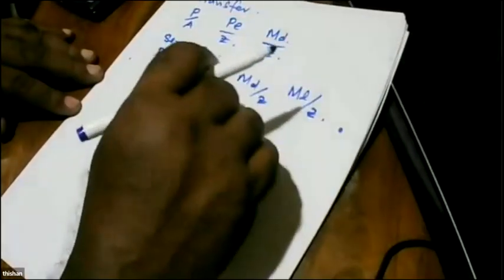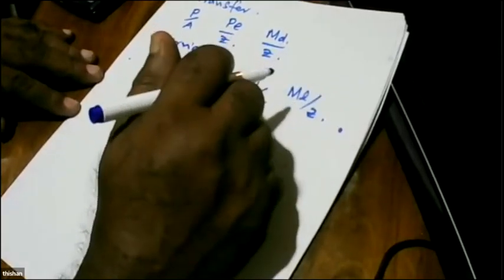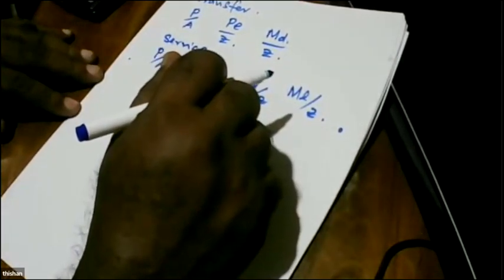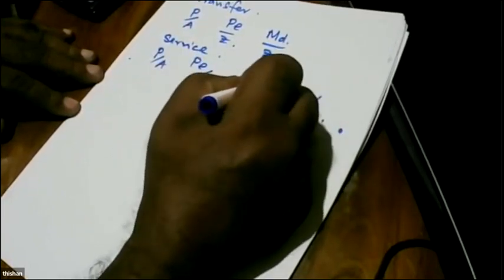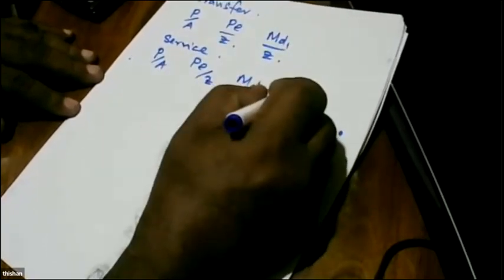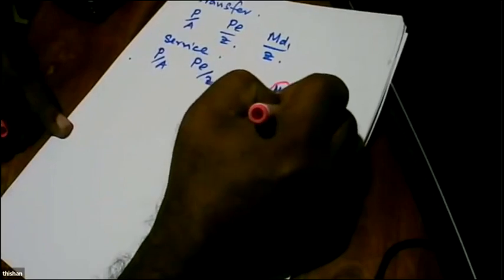Initially the beam is at the yard, no live load moment, only the dead self-weight. Now we have lifted the beam and kept it and finished the bridge. Now we get dead load, and we can also get two dead loads. One is the dead load applied as the self-weight, and then we can get another dead load. So we say MD1 and MD2. We are getting an additional component, like carpet that we place on the bridge, or some screed that we place on the beam. So whatever dead loads we apply later.